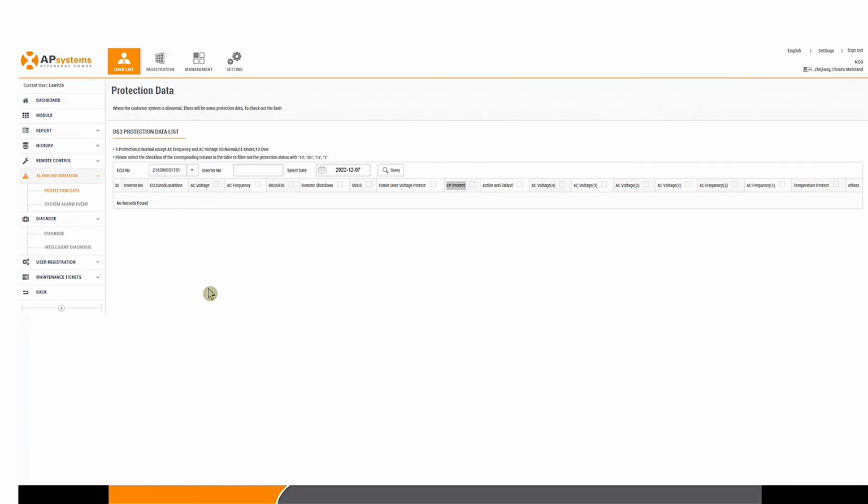Because remember how I said when you put in the max power, 625 watt inverter per channel is only 300. All right. The installer puts 625 on one channel, which is double what it's supposed to be. So things like that. That's why we don't give you access until we have some kind of foolproof way of fixing it. Yeah. Yeah.